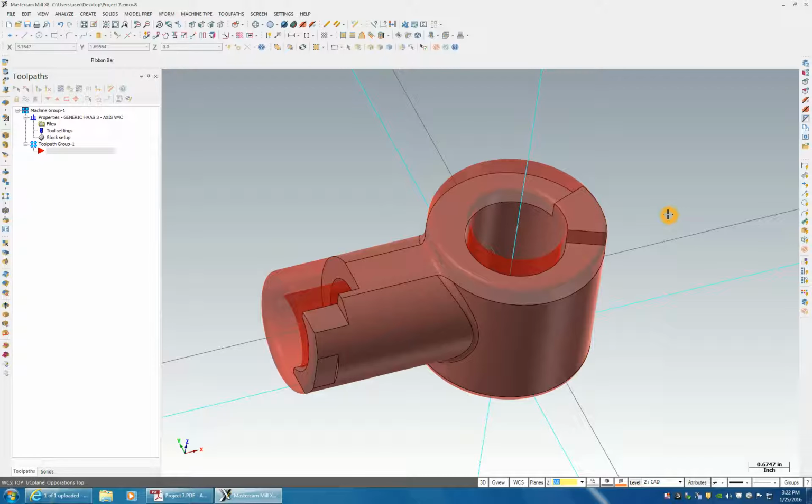This is likely not going to be able to be done in one tool path, because as we're coming around, we're going to leave, say right here where it's coming down off this face and down this way, a little bit of a fillet here. Then we're later going to have to come back and do another operation and come around that point.